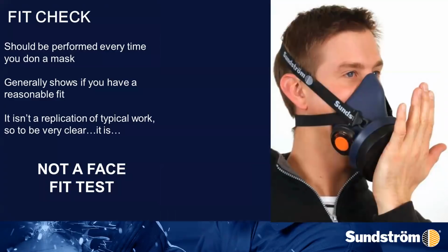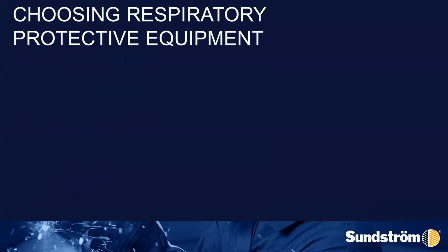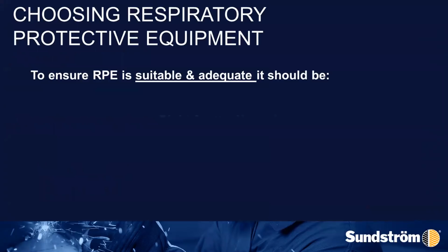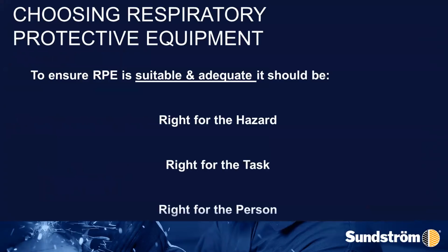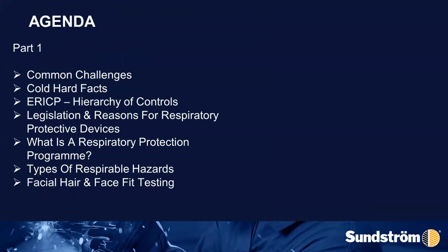But it's not typical of what you do all day long, right? Because you don't walk around with your hand over your mask all day, breathing in. So it's not a face fit test. It's just to check that the mask is sealed to your face well each time you put it on. So if we go through all of those processes, we should ensure that our RPE is suitable and adequate. We should have checked that it's right for the hazard, that it's right for the task, and that it's right for the individual person. So we should find that we're being compliant.